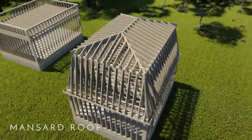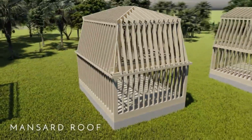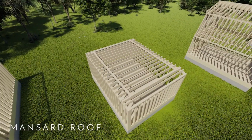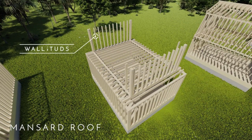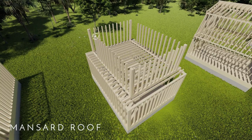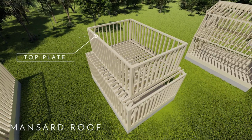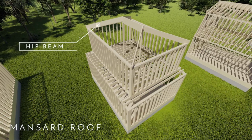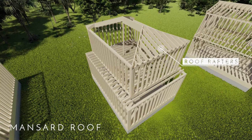Alright, so next up is the mansard roof. The mansard roof is very much like the gambrel roof. But instead of only offsetting two sides, we're actually going to offset all four sides, and we're left with this interior box here. It has the sole plate, the wall studs, and the top plate again. And this ridge doesn't span from exterior wall to exterior wall, it actually sits in the middle. Then we have four total hip beams which come from the corners of this box, and they go to the end of the ridge on each side. Then we have rafters that fill in these four bays.